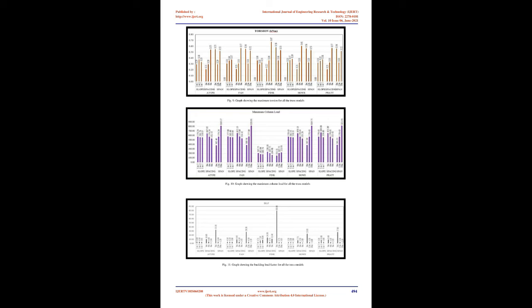The variations in slope don't induce any impact on bending moment. The maximum bending moment is experienced for slope 1 in 3, spacing 6 m, and span 18 m, whereas the minimum bending moment is experienced by the model having slope 1 in 3, spacing 4 m and span 12 m. When spacing varied from 4 m to 8 m, bending moment increases by 72%, revealing the ideology: larger the spacing, more will be the bending.